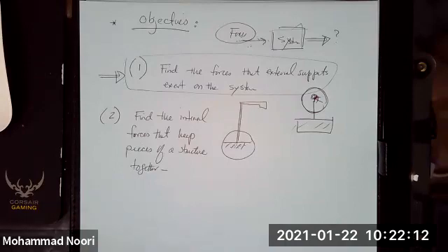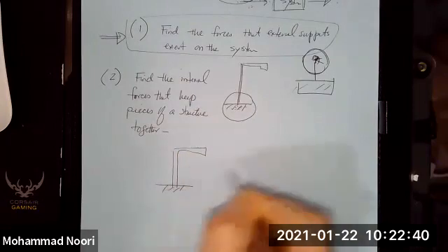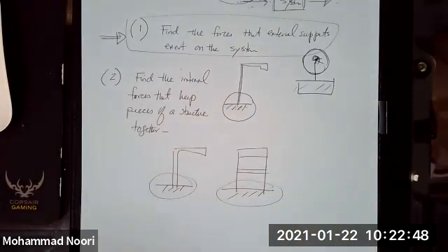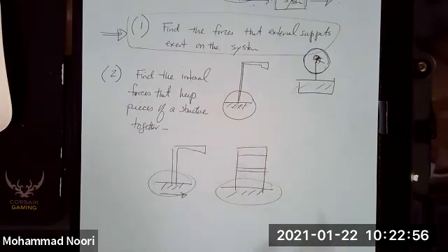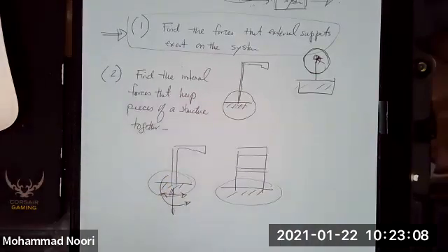My answer is as follows. If you look at the function that those supports play, of course, for the time being, let's focus only on two-dimensional structures, you see that these kinds of supports perform no more than three functions. Let me start with this. For instance, you have a light pole or a building. Either the support is such that it does not allow any motion in any direction. You have two directions for the forces and one direction for the moment. So no motion in this direction or in this direction takes place, and it does not allow even rotation to take place.